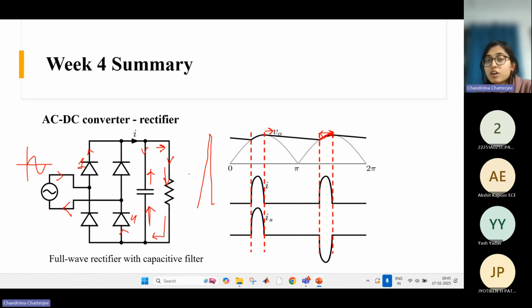Power dissipation is not happening because the voltage across this capacitor will be a DC voltage, but ideally the current through a capacitor in steady state will never have a DC component, right? In steady state, whatever current flows through this capacitor will always be AC in nature. So a DC voltage multiplied by an AC current will not result in any power dissipation, right?